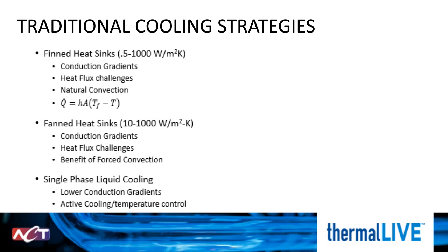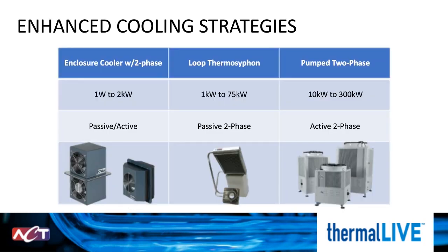It is therefore important to identify and understand advanced thermal strategies that support the cooling of power electronics when those typical off-the-shelf solutions fail. As mentioned earlier, today's webinar will detail 3 types of cooling strategies that were developed and produced by Advanced Cooling Technologies: the enclosure cooler, loop thermosiphon, and pumped two-phase. All 3 of these technologies leverage two-phase heat transfer.